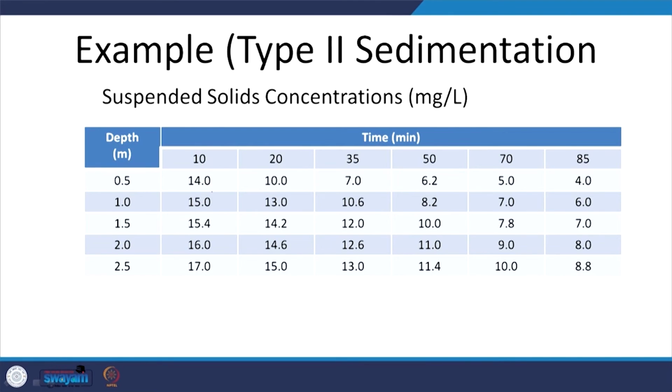So, they gave us the data, as in the suspended solid concentration at, say, 0.5 depth after 10 minutes. Obviously, as you see, the concentration decreases with time at the same depth, but increases with increasing depth. That is something we already discussed, so let us move on.